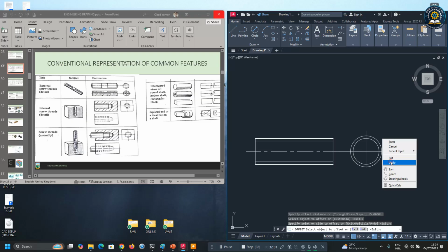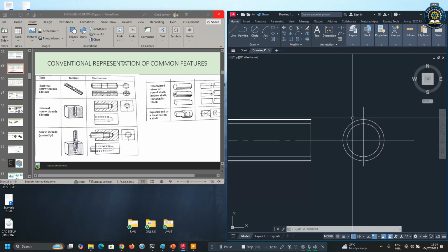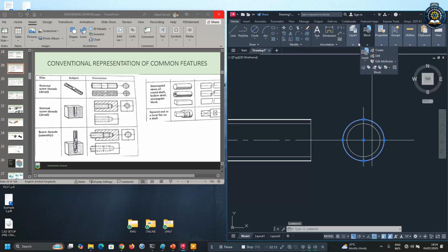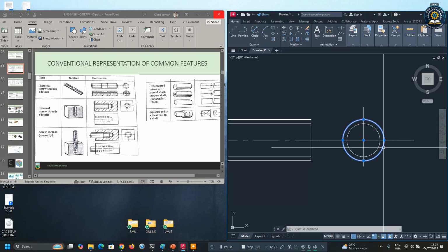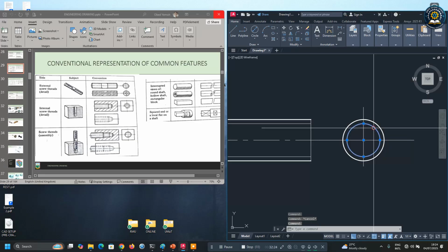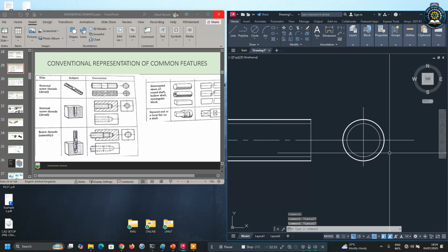Undo that, 5. Right, now our circle, the thin one is incomplete, but the thick is complete. So let's highlight them and change them. Thick line. For the external one, press escape to move that, then highlight this, and then we will select thin. All right, thin line for this. So thick and then thin.